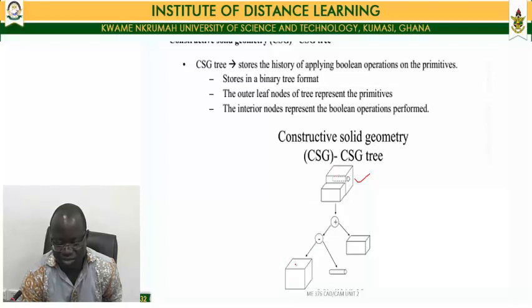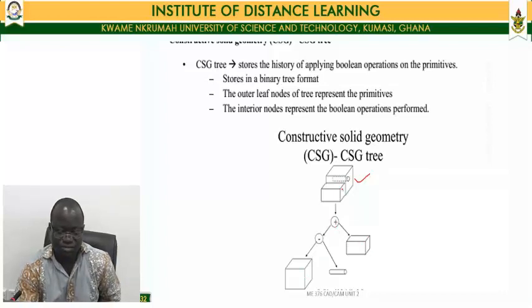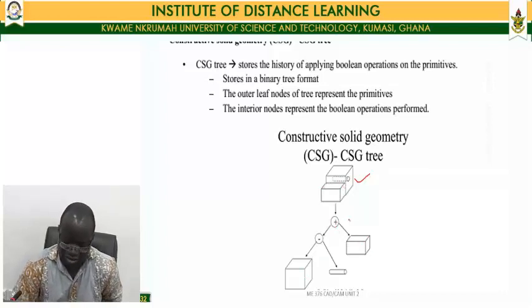So we subtracted this cylinder and created a hole. And then we eventually added this side of it, which is here, to form finally this. So you see the three forms show the Boolean. This was added, this was subtracted to generate this. So this is a typical constructive solid geometry tree.